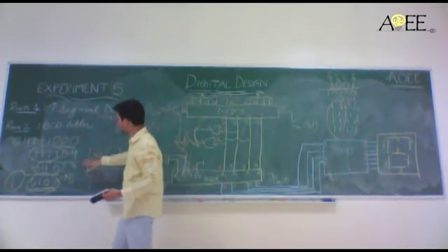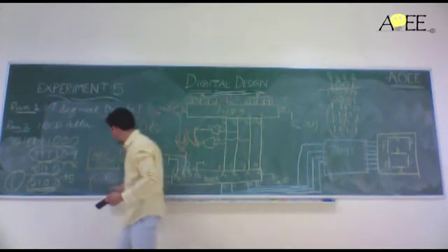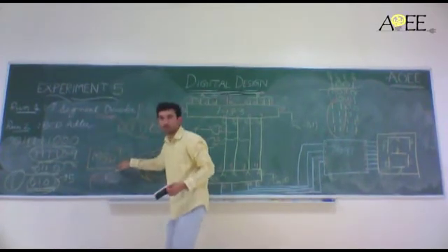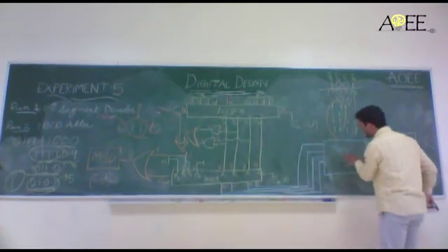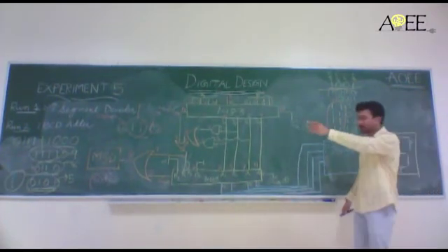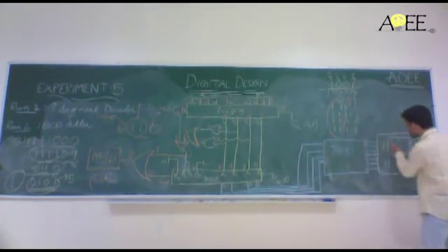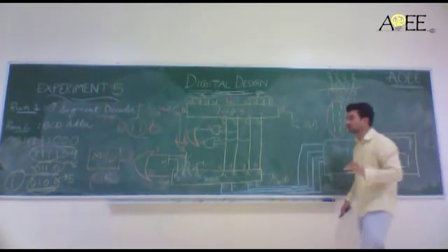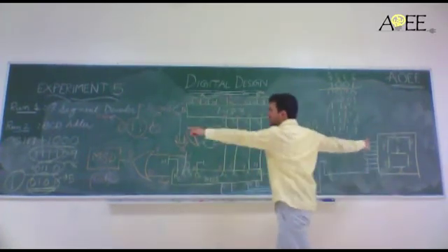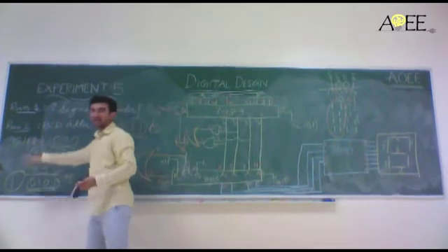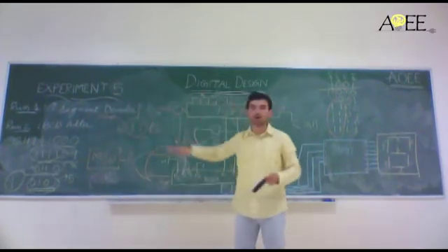Our case was 15, right? To denote it was 15, this will be turned on. And the remaining digits will go into 7447, which has 4 inputs converted to 7 outputs and displayed on the display. So 1 and 5 will indicate that it was 15 when 7 and 8 were given as inputs. So this is how a BCD adder works.